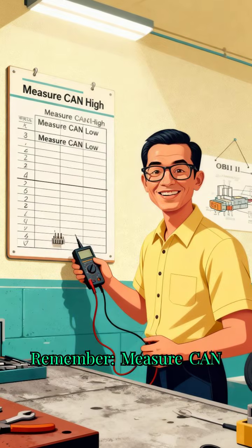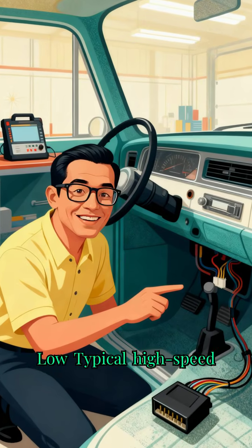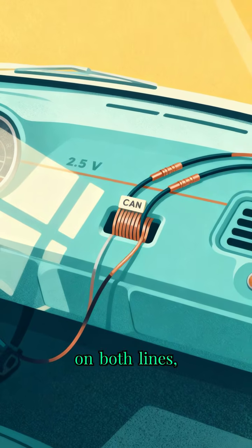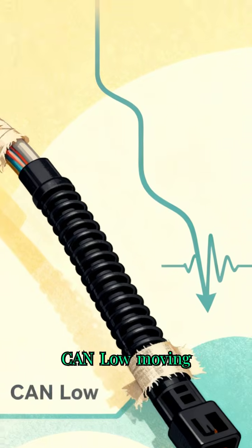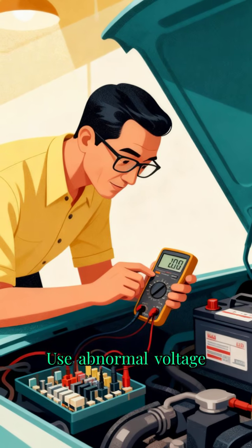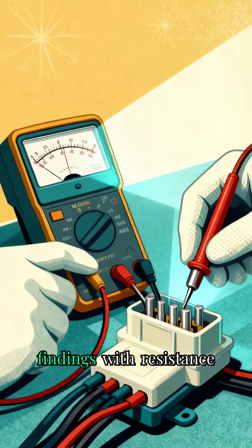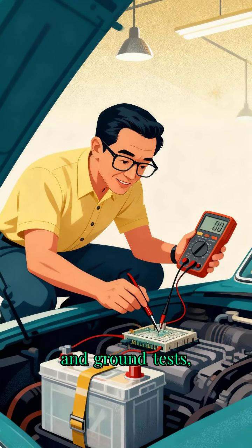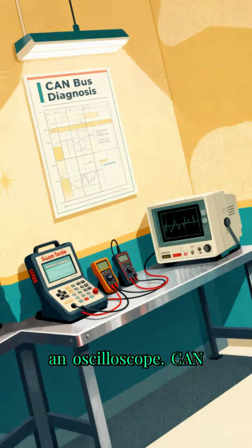Remember, measure CAN high, measure CAN low. Typical high-speed CAN networks rest near 2.5 volts on both lines, with CAN high moving upward and CAN low moving downward during communication. Use abnormal voltage readings to guide your diagnosis, but always confirm your findings with resistance checks, module power and ground tests, a scan tool, and, when appropriate, an oscilloscope.